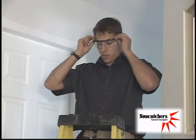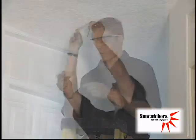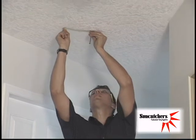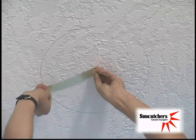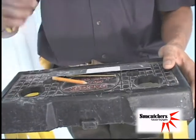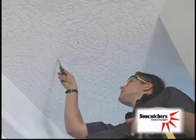Put on safety eye protection. Using the supplied template, a pencil and a screw, draw a 13.5-inch circle on the ceiling, using the pencil mark as the center point. Using a drywall saw, cut the circle out, just slightly wider than your pencil mark.